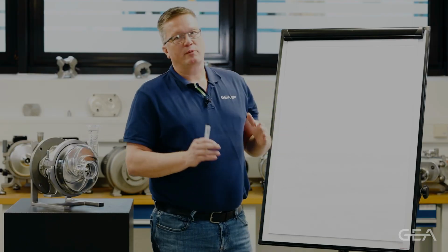theoretical part. So NPSH, net positive suction head, is calculated out of two NPSH values that we have when we want to select a pump. One is the NPSH available. This comes from the unit, your installation, and the NPSH required. This is what the pump requires to transfer the liquid, because the pump can only handle liquid and not vapor. So we need to keep the liquid as liquid, and this is required by the NPSH.